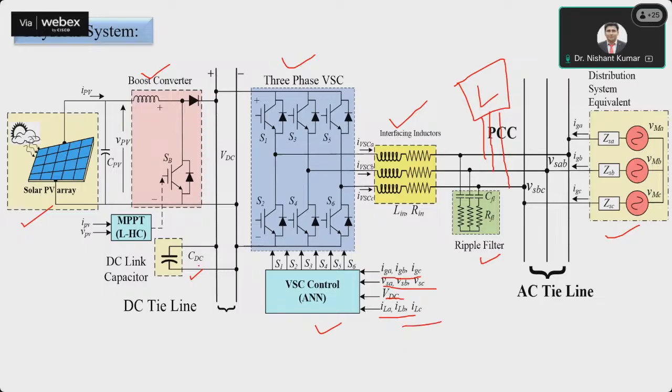Another side we have a DC link. If you want to attach the load on this side also, fine, you can attach it here. Since we have a panel here, this will require one MPPT algorithm, and the MPPT algorithm will decide the pulse for this. So again some sensors are required here, meaning DC PV voltage and PV current. Two sensors are here, and on this side you will see a total of 10 sensors. Right? 10 plus 2, a total of 12 sensors.